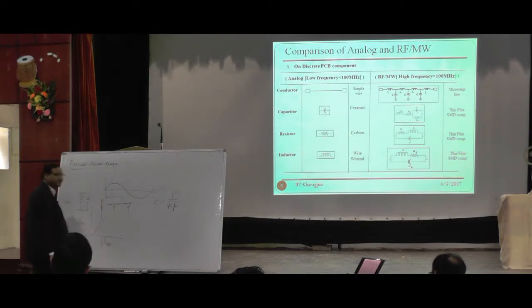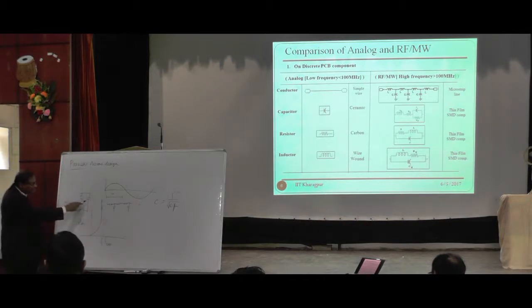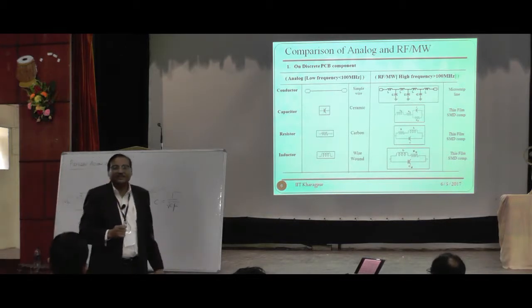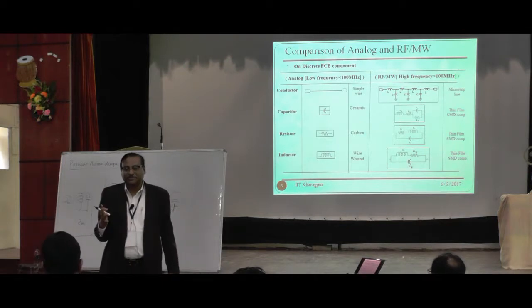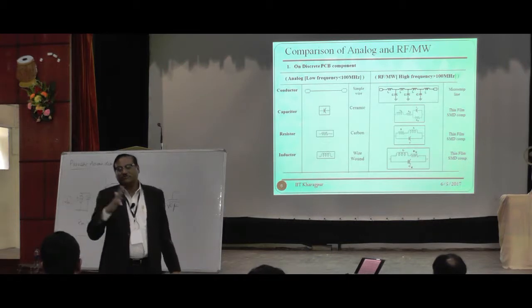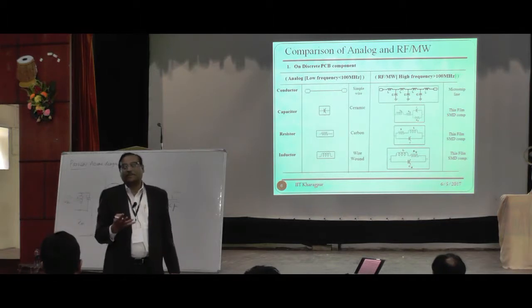So think of it, this is the frequency which is called the self-resonance frequency. So if you are designing something where the self-resonance frequency, because of this LC network, you are not aware of this capacitance, your impedance, whatever you are thinking of the inductive one, will basically be a capacitor. So maybe your self-resonance frequency of that inductor was 25 gigahertz and you want to work on terahertz. So the inductor will behave just as a capacitor. So that kind of confusing state will come while you design. Negative value will come. And you have to be aware of that parasitic effects.